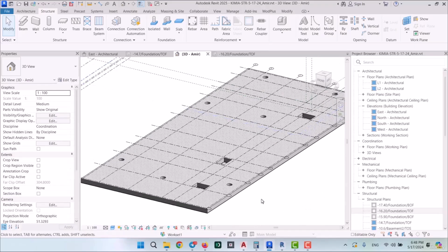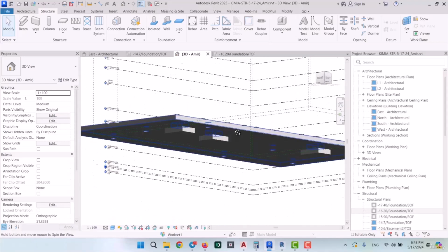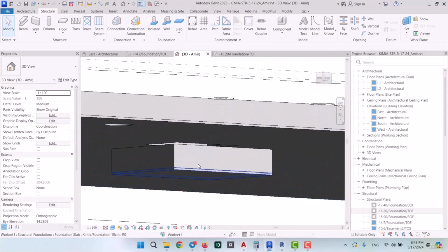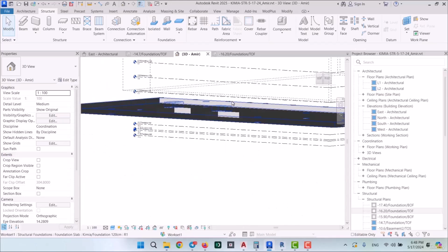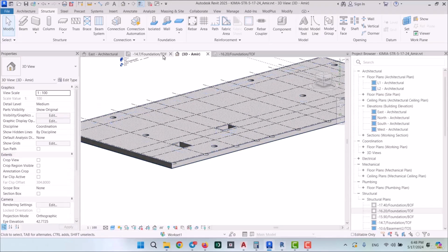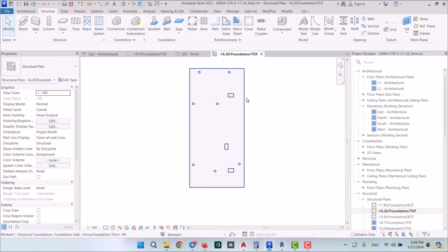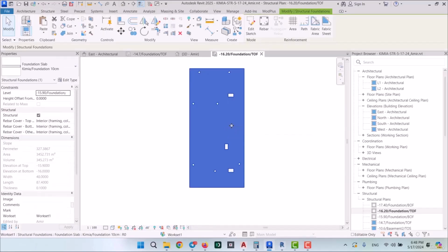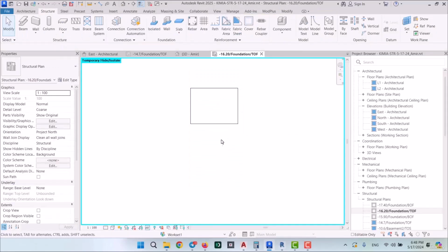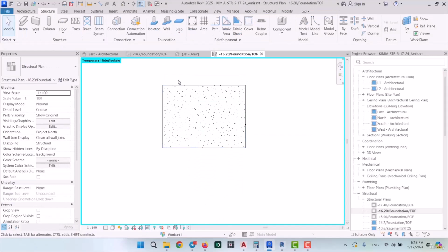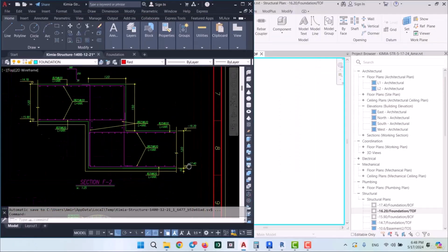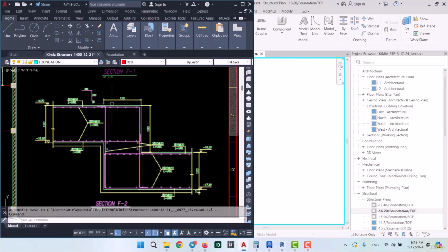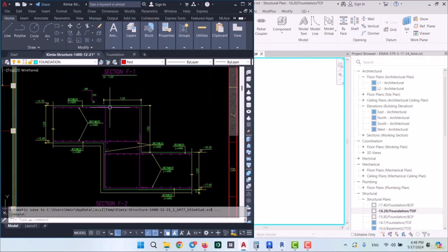Now, our work is almost finished. The only thing that's left is we need to also put the wall border to cover the distance between these two. So for that, we're going to have to go over to this view. And we're going to have to draw the wall over here. Now, also, if you take a look at this plan, our wall needs to be 120 centimeters thick to go around this area and fill in the distance.